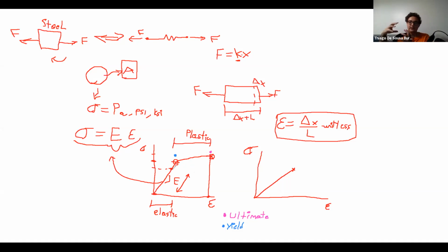So if you think about it in a car crash, your car will deform significantly. So it's going to enter the plastic region. The reason it does that is because it's dissipating all of that impact energy by destroying itself instead of the energy going onto you. So in composites, we absolutely do not have that.